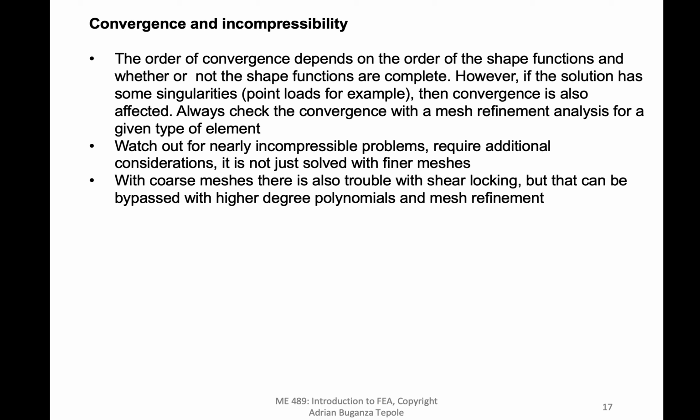And for the quadratic shape functions, the order of convergence was greater. And you have to be careful because that's not always the case. So the convergence, how fast your solution gets accurate, yes, it depends on the shape functions that you're using, but it also depends on whether or not your problem has singularities.